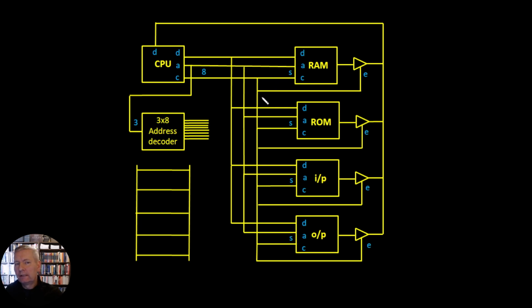Now, I know that we've already built a 16-bit machine, but let's talk through this in terms of an 8-bit machine first. If we were to take the 3 most significant bits of 1 byte into the address decoder, then we would have the 5 least significant bits of the byte that would head into the RAM.